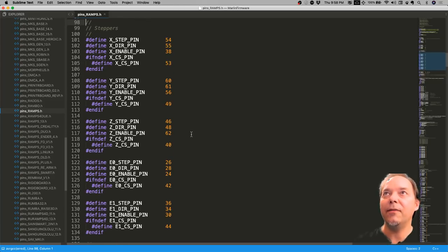So with every stepper, you have enable, which means the stepper is turned on and powered and getting warm. You have direction, so when we do a step, which way is it going to go, left or right? And a step pin, which when we trigger it, either goes high or switches to low, or does a high then low. Depending on how your stepper driver is implemented, if it changes from low to high or high to low, it's a step.